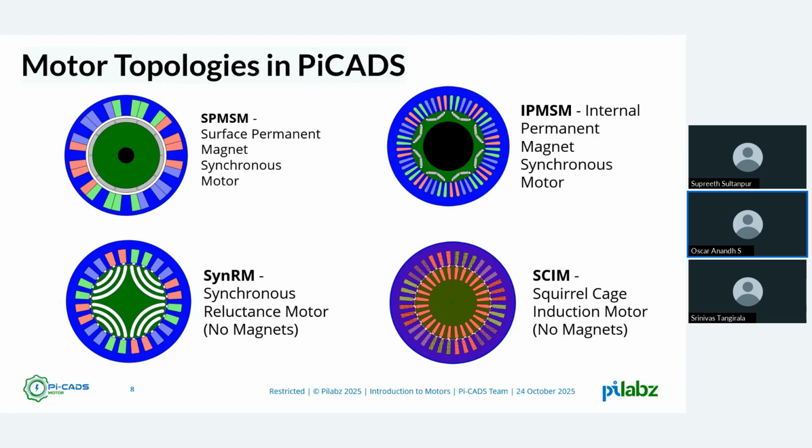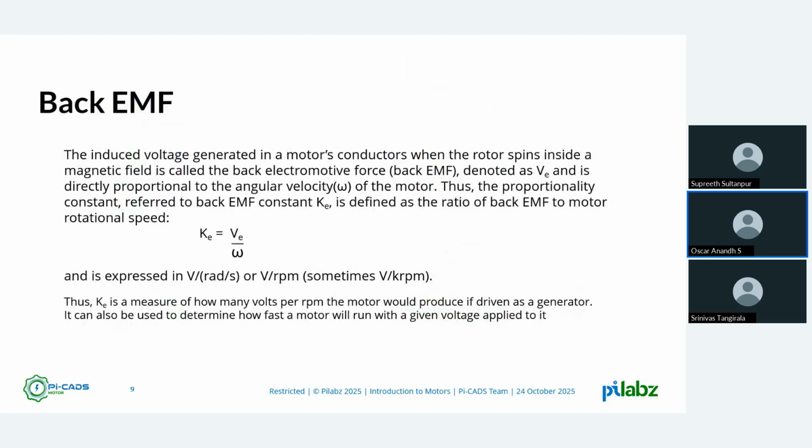Yes, sir. As sir said, air gap is very much important. It should be between 0 to 1 mm. If the air gap is so high, the magnetic flux will not pass, and the rotor will not rotate. If it is too close to the stator, it will crash the motor. So it should be very precise. Okay, then let us go on to the next slide.